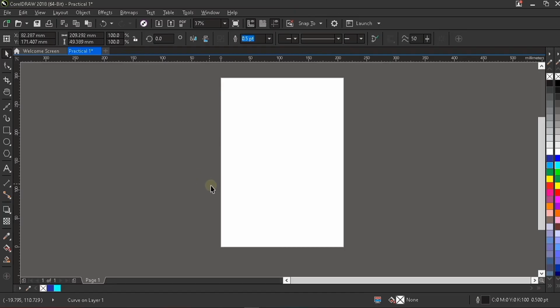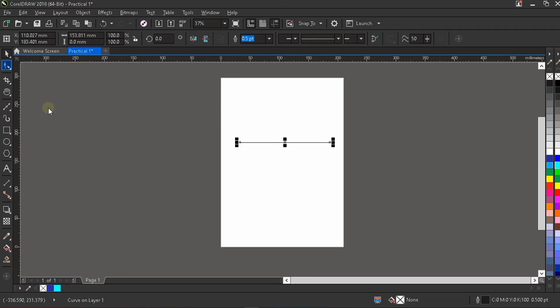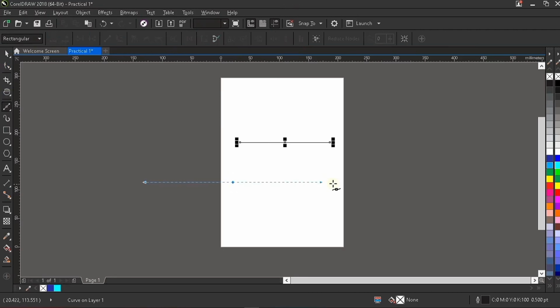Okay, so I'm going to use that bezier tool again to draw a horizontal line, holding down my Control key. Have you seen? The line is very straight, I'll click once. I'll drop the tool, select it again, and draw another one. The plus sign is straight where that line is. I'll click once, the straight line. For the vertical line, I'm going to draw the same way, holding down the Control key. I've not dropped the tool, that's why it joins. I'll drop it and select that tool again. Vertical line, I'm going to click once. The plus sign is straight where it is. I'll click once, that's a straight line.